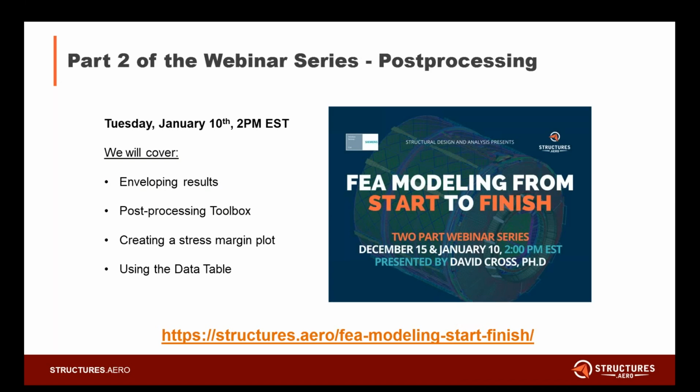And so part 2 of this webinar will take place on January 10th. And what we'll do in that webinar is finish this one up where it'll be fully connected up, and we'll run the analysis and then check through all the different results. So we'll look at contour stress plots, we'll look at C-bush forces, how to utilize the data table to extract results information, which you can then put in Excel and manipulate or pull into other tools that you might have, and enveloping results so that you can look at your max and min stresses, things of that nature.